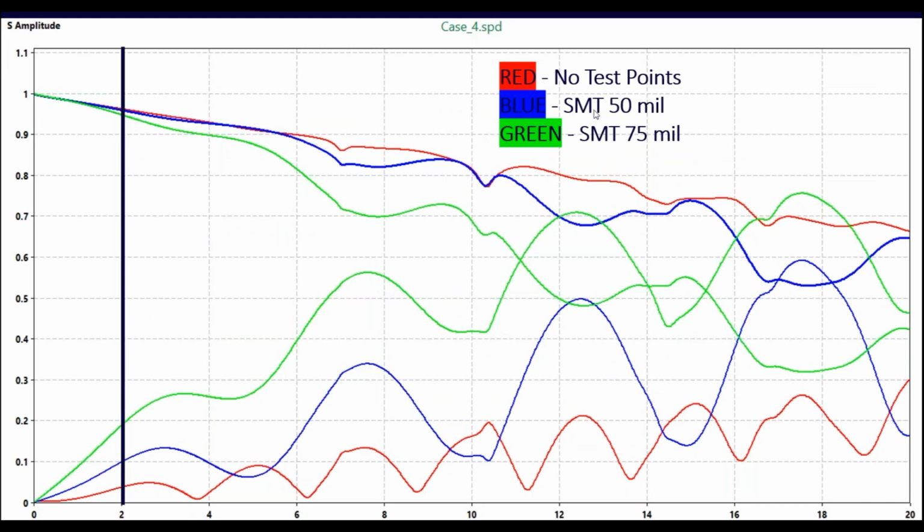Because what I'm concerned about is that, again, I want 5x what we are starting with. So we had a 15 mil width line. Well, what if it's now 5x? So we did a surface mount at 75 mil. You can see now the green is the baseline, here's the 50, and of course the red line is the total baseline. But the 50 was the last one we just saw here. So let's introduce the 75 mil here.